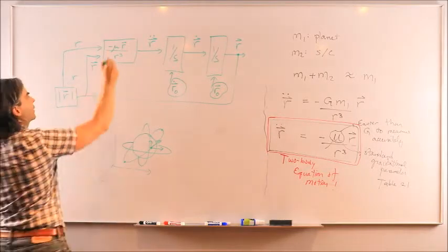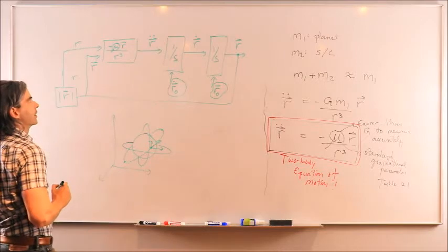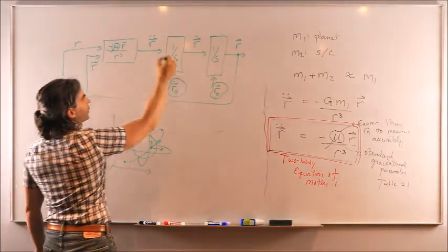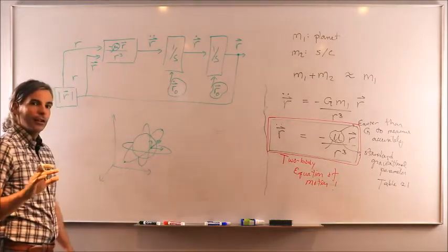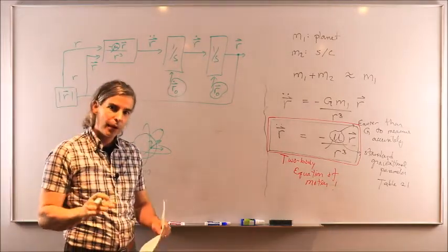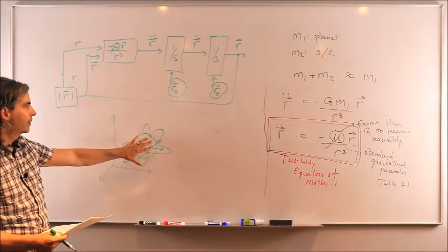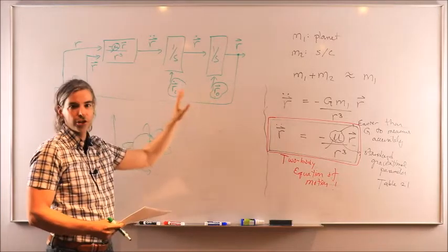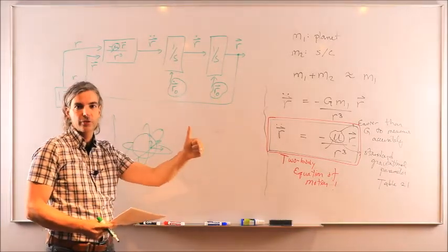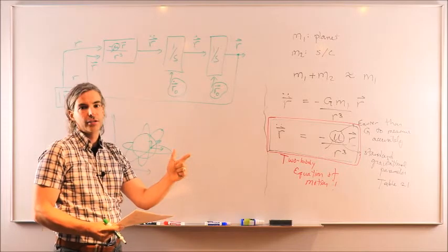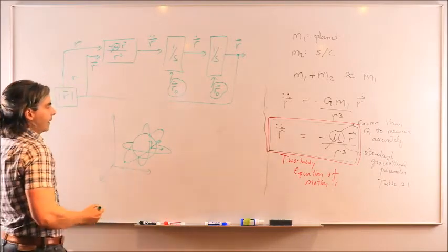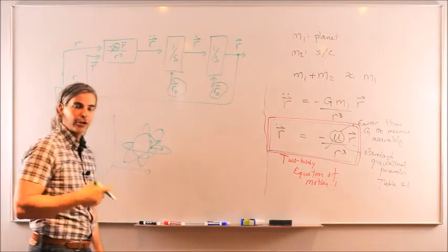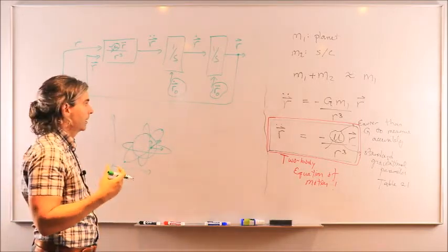All right, the rest here, the minus mu is just a constant. The position vector is only a byproduct of the integration process. So as the three parameters that you can play with to generate a given type of orbit, again, all you have to do is to carefully select those two sets of initial conditions: initial position vector and initial velocity vector. Okay? Now, selecting those two quantities is not a trivial process. It could be very complex.